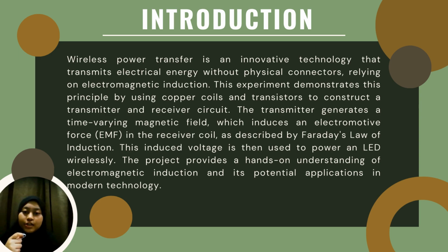So for introduction, what is wireless power transfer? Wireless power transfer can transmit electrical energy without a physical connector, relying on electromagnetic induction. In this experiment, we use copper coil and transistor to construct transmitter and receiver circuits. The transmitter generates a time-varying magnetic field that induces an EMF in the receiver coil, as described by Faraday's law of induction. This induced voltage is then used to power an LED wirelessly.